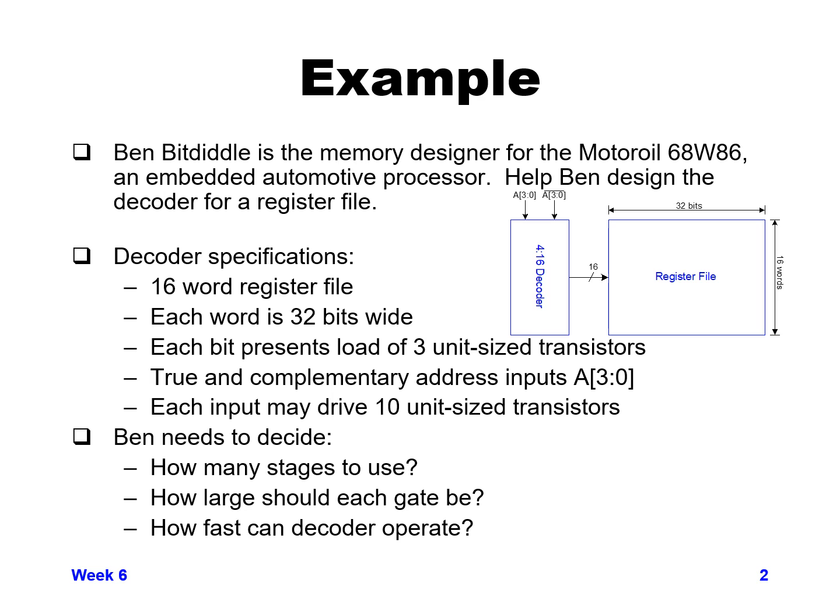So the delay through that type of gate, minimum size inverter with no load, is our unit delay. So these are the things that we're trying to figure out, and we'll go into that in the next several foils.